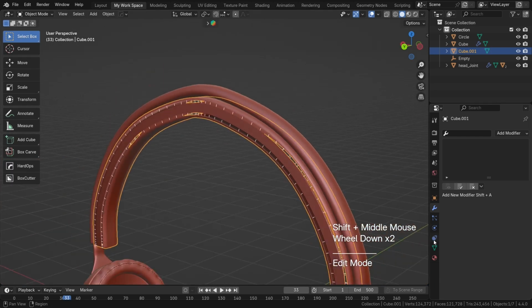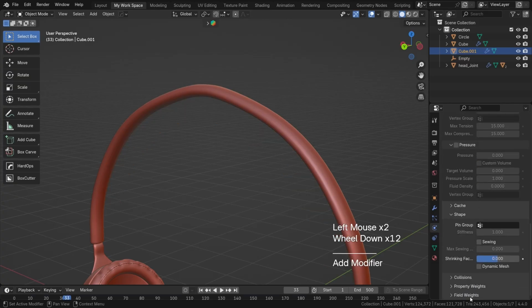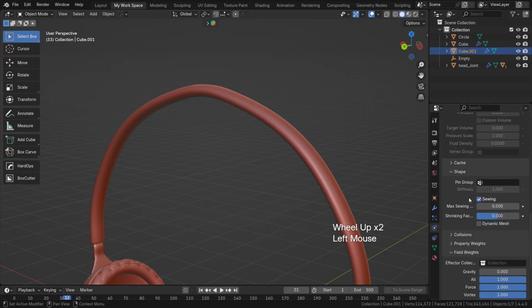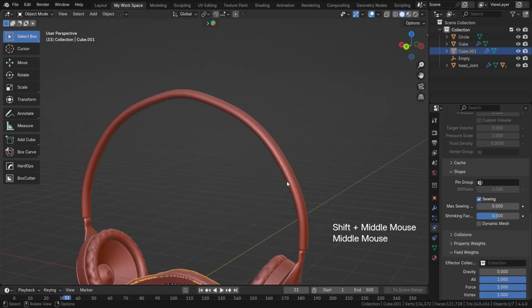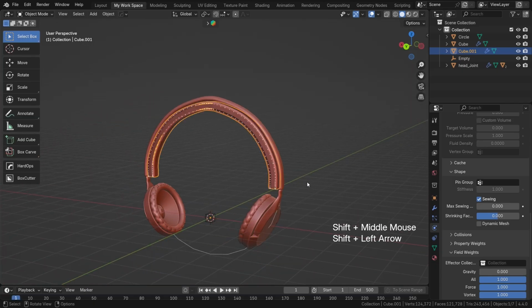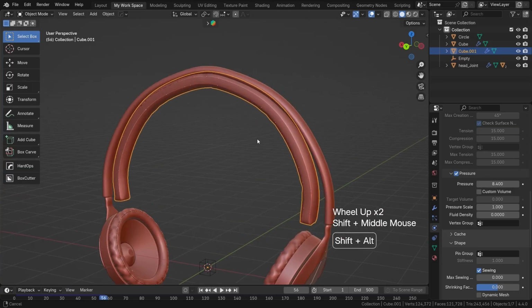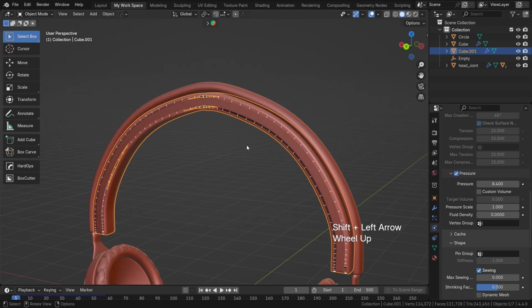Yeah, I'll go in the physics tab, in cloth simulation. Here first of all we have to reduce gravity all the way to 0 and sewing effect. Why? Because we have already created some loose edges. Yeah, and we'll apply some pressure on it like that. Now we'll run the simulation like that. And guys, first of all we'll create a pin group also.